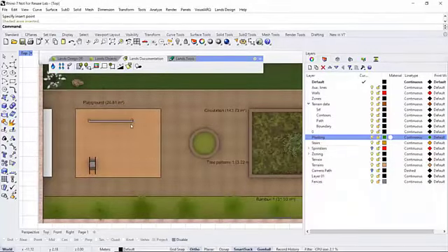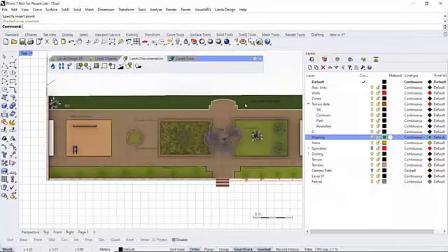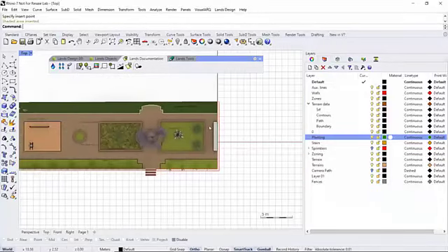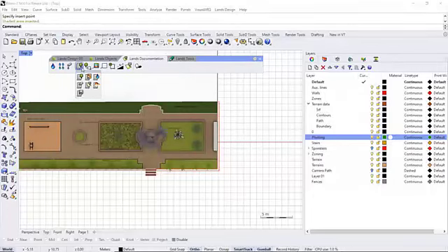All right. So we've got all the zones created. Here we could already insert a list of zones. We already have an idea about the total square meters that we are using for this project. So here under the documentation toolbar, we can find the zoning list.